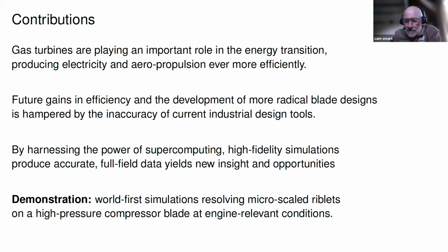it had guns in front of those air intakes, and when the guns were fired, shock waves from the muzzles went into the air intakes, got into the first stage of the compressor and stalled the blades.